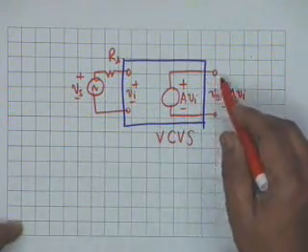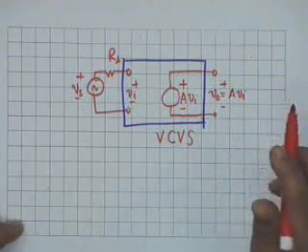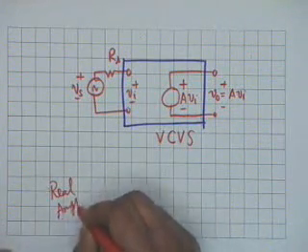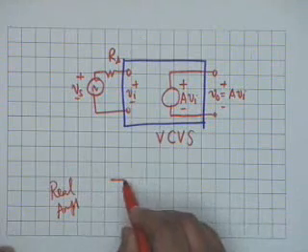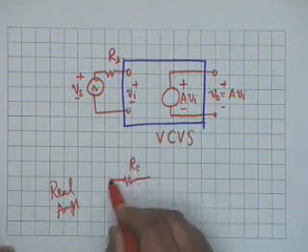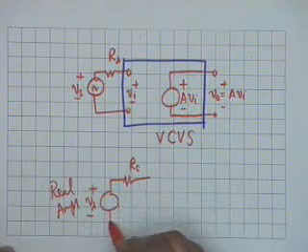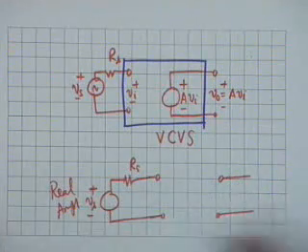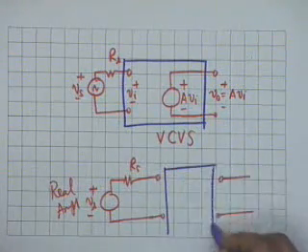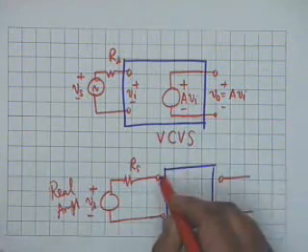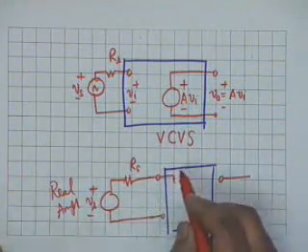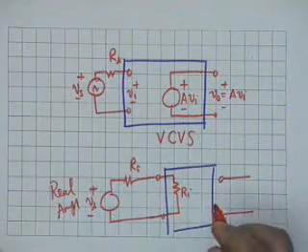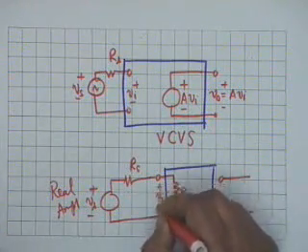Similarly, the output resistance of a real amplifier is not 0, but a non-zero quantity. Therefore, if I consider a real amplifier, the model of a real amplifier shall be like this. You have a source Vs that connects to the real amplifier, in which the input resistance is not infinity, but let us say some value Ri, then this voltage developed is Vi.